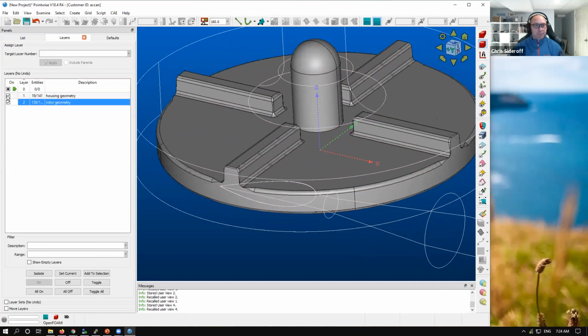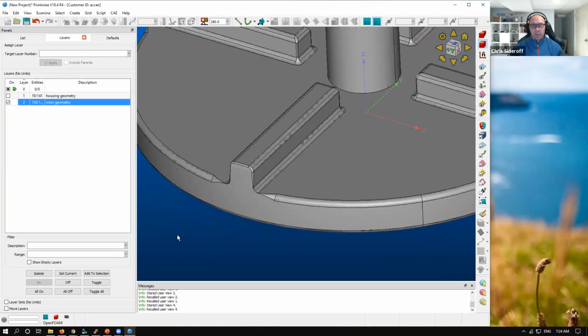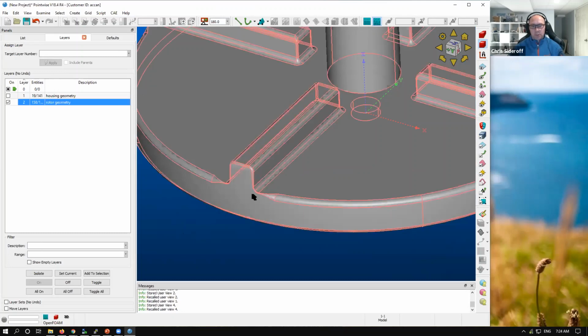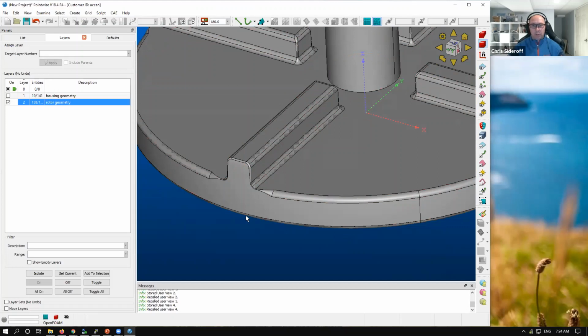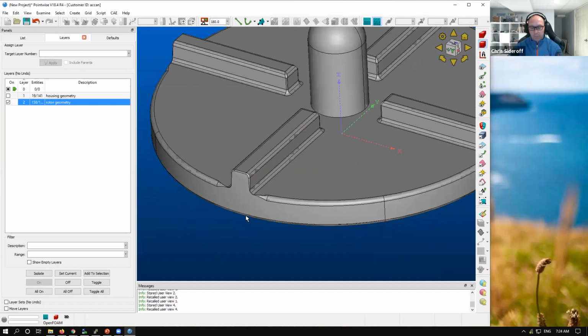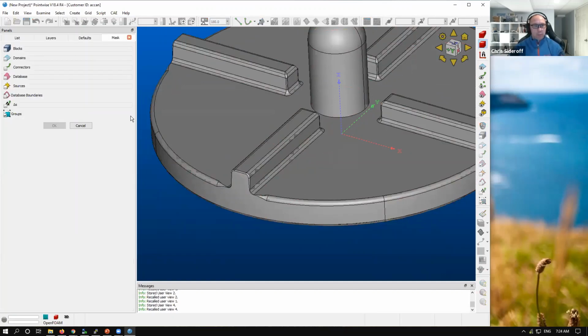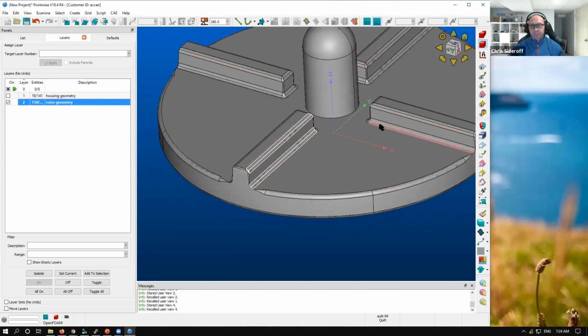For example, on the rotor here, we can see that on the fillets and on the rounds, there are two surfaces. It was just split for some reason. And you don't really need a grid pair or points there automatically. We can easily constrain the mesh to follow the curvature anyway. So it's just going to get in the way. So what I'm going to do is join up these surfaces into single surfaces.